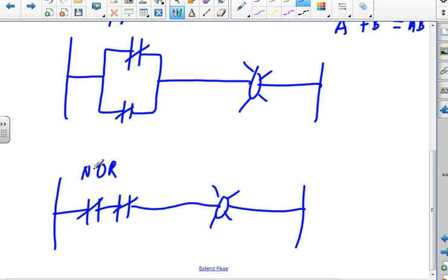And if the temperature gets high enough, then my outlet valve comes on and I can let it come out. So I want it to come out at the right temperature. Notice that I'm doing a control power transformer. This time I'm not coming directly off L1 and L2, but I'm doing a control power transformer just like we do in the lab.